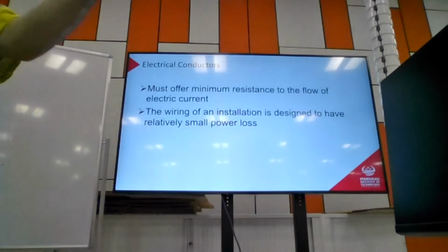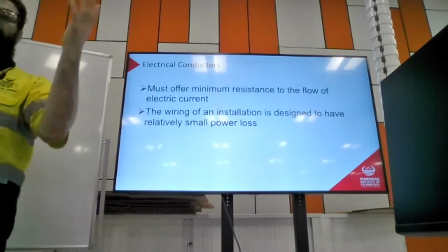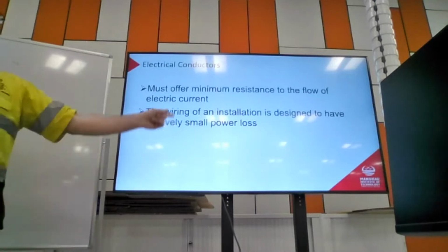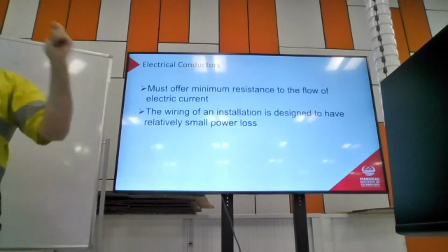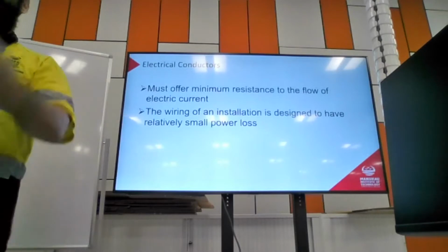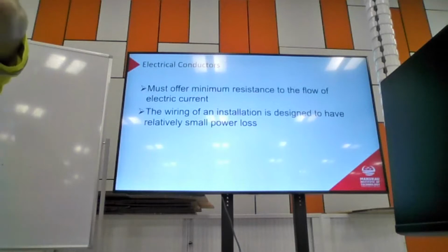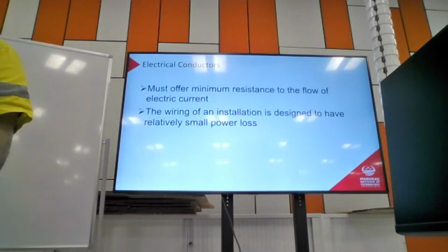So if I have a volt drop across a cable and a certain amount of current running through it, then I'll multiply whatever that volt drop is times the current running through, and that's how much power is being lost in that cable, right? Does that make sense? So if I've got 10 amps running through a cable from this end of the room to the other end of the room, and I've got a 2 volt drop from one end to the other, then that means 10 times 2. So I've got 20 watts of power just being consumed in the cable. It's not doing anything useful, but I've got to pay for that power, right? So every time I've got that circuit switched on and I'm running that 10 amps, then that 20 watts that I burned in the cable is lost to me.